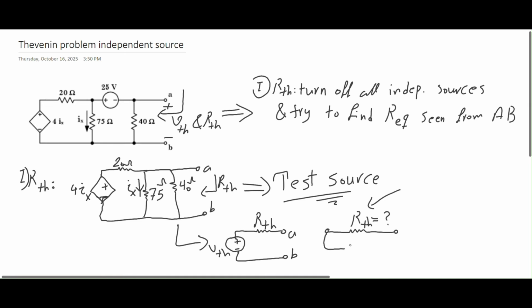You connect this resistor to a current source, let's say 1 amp. As you know, we have those power sources in the labs where you can set the current, and we also have meters with two probes that you can connect to the ends of the resistor and read the value of voltage.